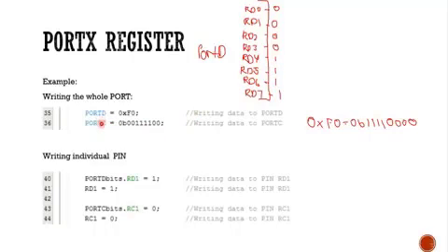And then you can also write by using binary format, port C. So for this case, port C, you can see here bit 0, the value is 0, bit 1 is 0, and then bit 2, bit 3, bit 4, and then bit 5, all will produce 1. And then the last two, bit 6 and bit 7, will write 0, 0 here. So this one is according to the number of the bit.